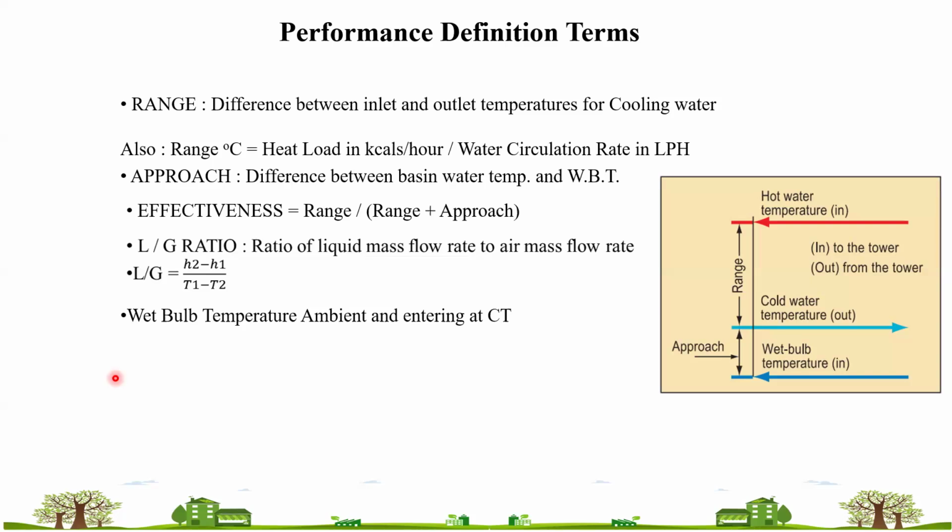Previously, when you provided a wooden cooling tower, after a certain year of operation, fungal or algae growth was there, and algae growth causes another problem: blowdown has to be done, or the cycle of concentration has to be maintained in your cooling water again and again. So the water quality deteriorates. So nowadays they have shifted to FRP.